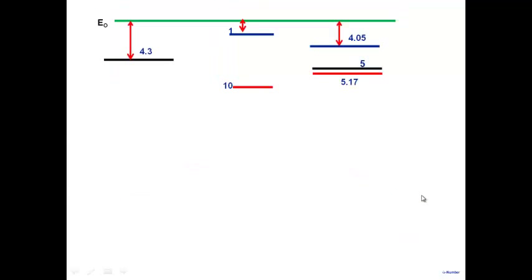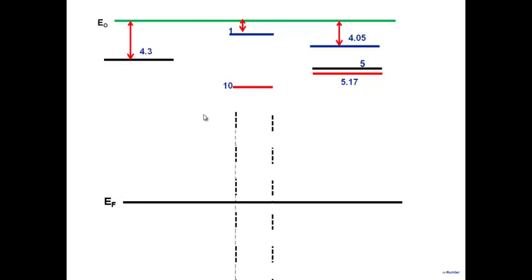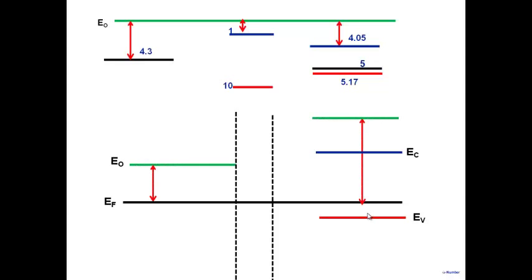After equilibrium, we know that the Fermi level is going to be flat everywhere. So that's what we do. We draw constant Fermi energy, then we draw the interfaces. We have an interface here, we have an interface here. Far away from this particular interface, the semiconductor is going to be the same everywhere. So once we draw the Fermi energy, we can draw that EV is going to be 0.18 away from here. We know EC here, so that we can draw easily.